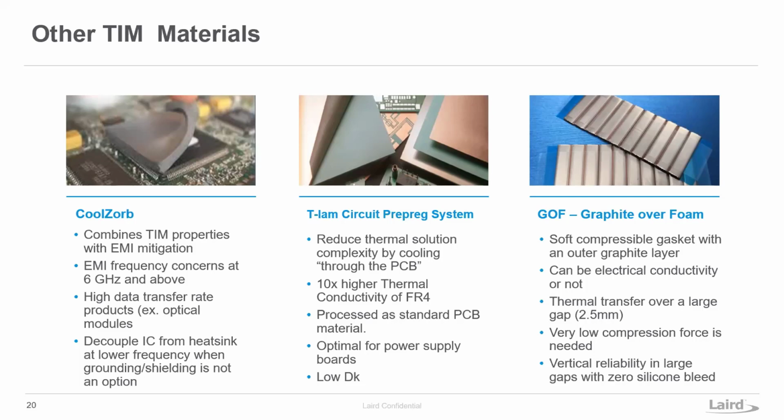Finally, we have our GOF, which is a graphite over foam product. We are using the high thermal conductivity in the XY direction of synthetic graphite to transfer the heat around a foam core. And this foam core provides very low stress on components. It has great spring back, and is great for applications where you've got large gaps.